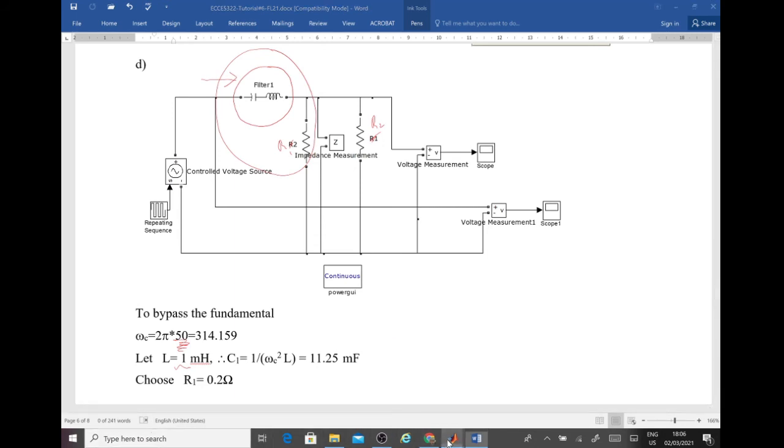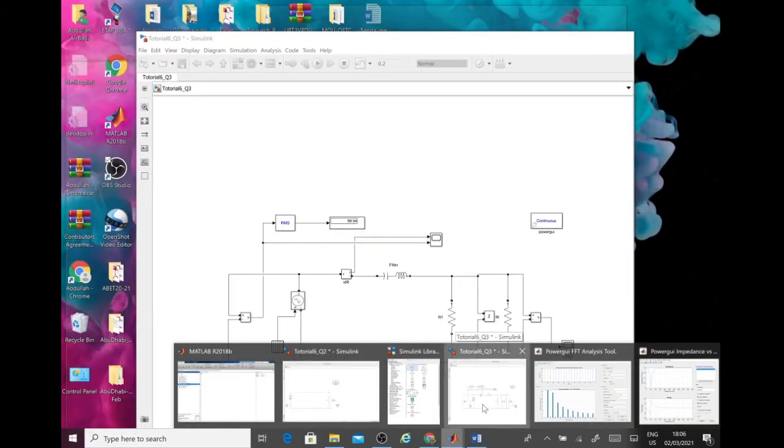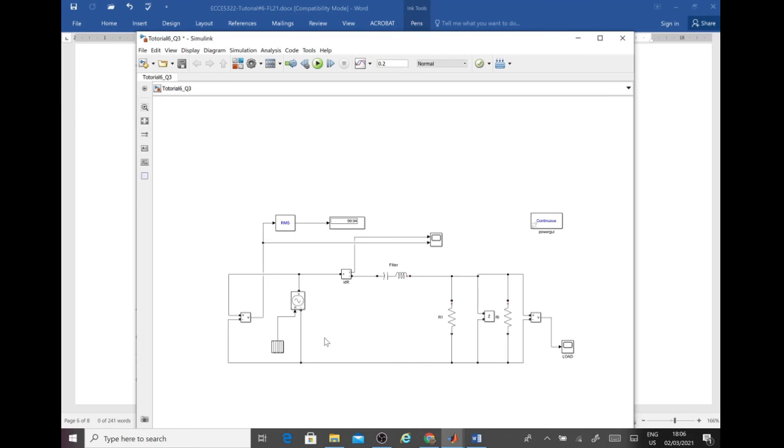If we do the simulation in MATLAB, again this is the MATLAB file. Okay, so this is our voltage source, this is our load. So of course I connect over here a meter to measure the current. I connect over here, let us say, another meter to measure the root mean square value of the source voltage, and so on. Okay, but those are the main components. So those are the filter components. Now let us do the simulation. So click on simulation, finish.